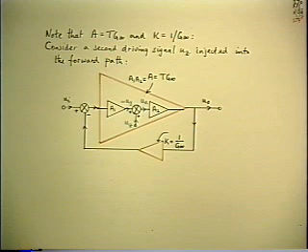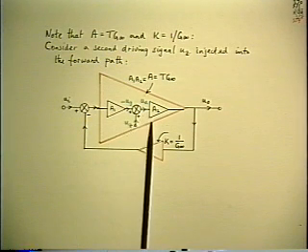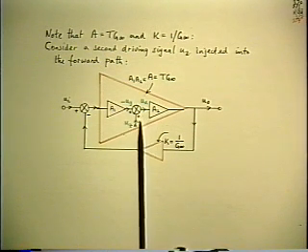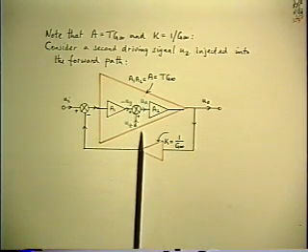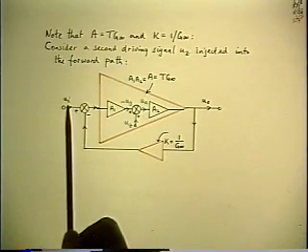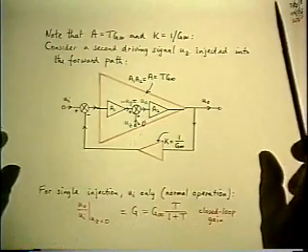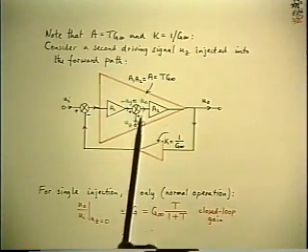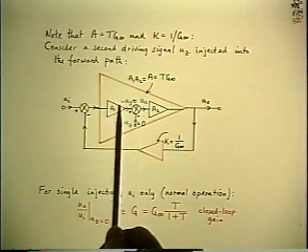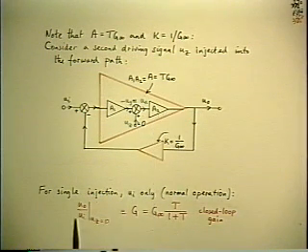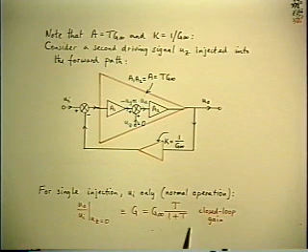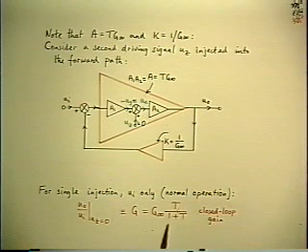Okay. The normal operating condition, just to take the reference, is when the amplifier is operating closed loop, you're not injecting any UZ. UZ is 0 and the UI is not. And in that normal operating condition, if UZ is 0, UX equals minus UI, because the signal just goes straight through. And we know under that condition that the closed loop gain of the system can be written G infinity times T over 1 plus T. That's the final answer we're looking for.